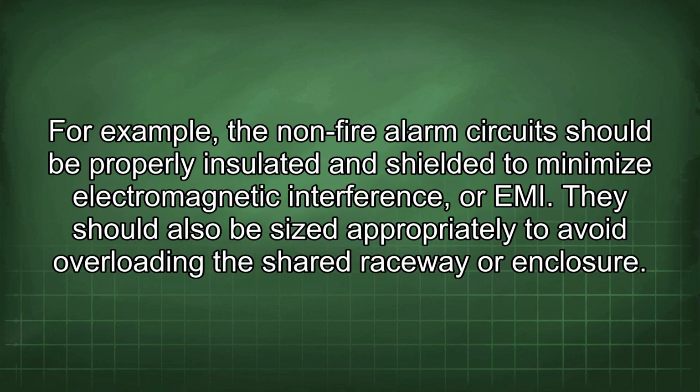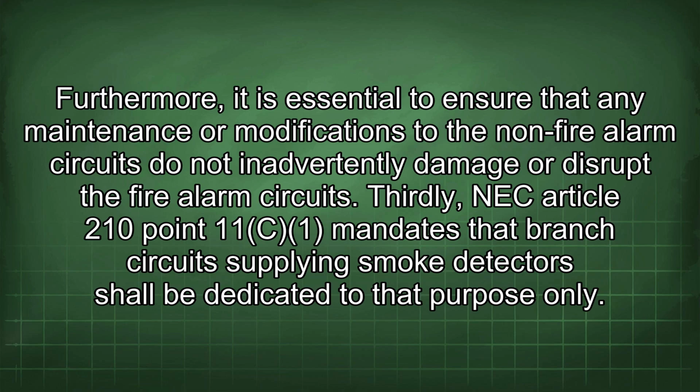For example, the non-fire alarm circuit should be properly insulated and shielded to minimize electromagnetic interference, or EMI. They should also be sized appropriately to avoid overloading the shared raceway or enclosure. Furthermore, it is essential to ensure that any maintenance or modifications to the non-fire alarm circuits do not inadvertently damage or disrupt the fire alarm circuits.